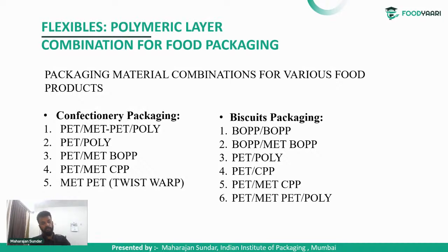It should give a good printable surface, for communication and information sharing purposes. And third is sealing. Once the product is packed and printed, it cannot be left open. For the product to retain its original state from manufacture until the end user, it should be properly sealed. Mostly the inner layer of a packaging material will be a sealing agent, and it should give heat seal stability. The seal should withstand for a long time until someone tries to open it.